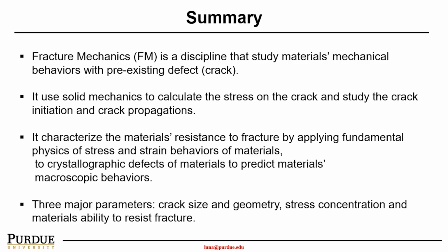To summarize what we have discussed in this lecture, a couple of take-home messages I would like to re-emphasize. First, failure is not fracture. Failure is when a material loses functionality. Fracture means the material breaks into pieces. Fracture mechanics is a discipline that studies material mechanical behavior with pre-existing defects.